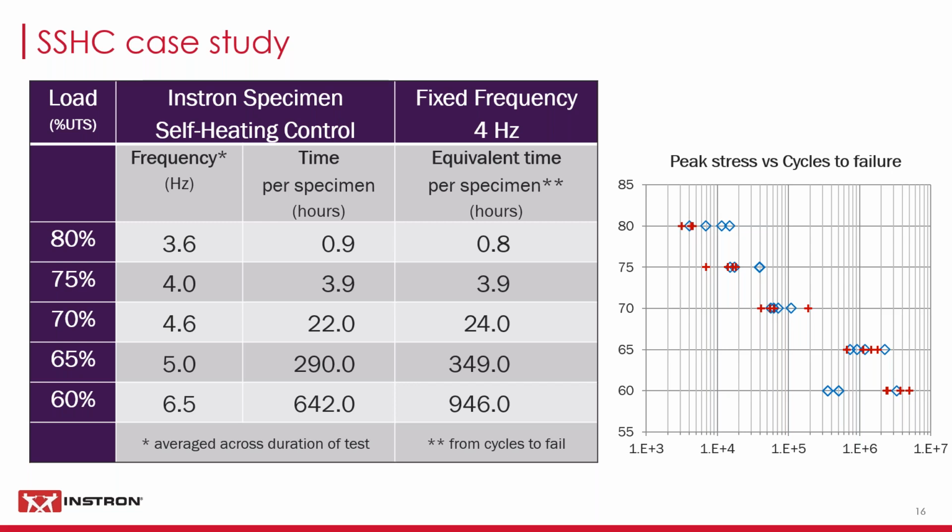Well, I mean, it's a good suggestion. I have discussed that with people in the past, but I've never seen anyone actually implement it. So what we're talking about here is a capstan grip. So we're talking about a thin filament that will bend round, and you've got a wide radius load in it, and it's tension only grip. My caution on that would be actually about fretting and sort of frictional damage at that end loading point.